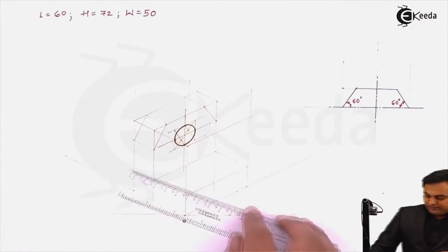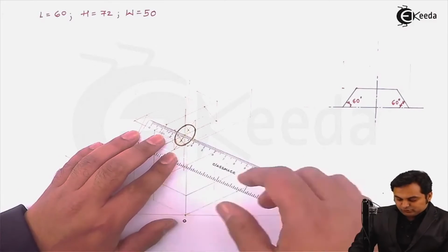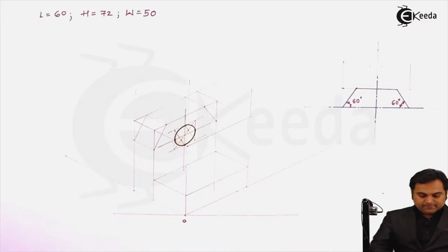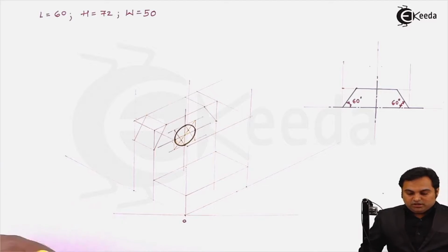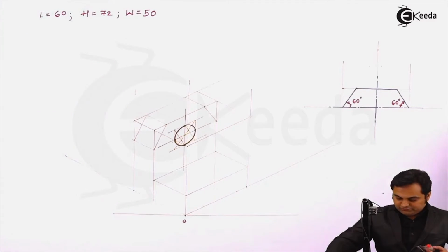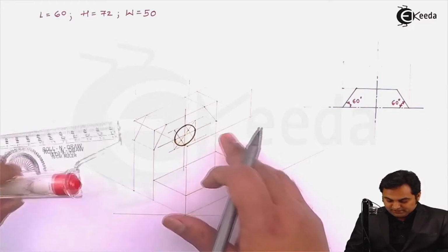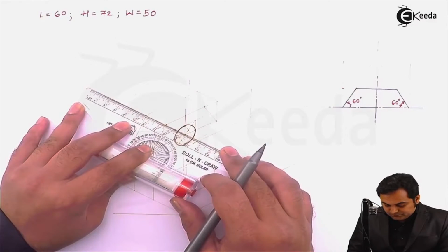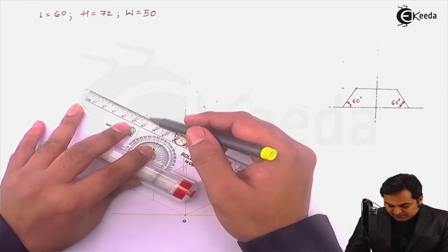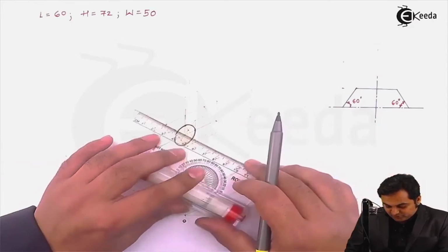And suppose instead of that, if I take the top center ahead and try to draw it, I'll explain how it should be done, because we have to check the depth whether the circle would be seen along the depth or not. For that, instead of taking the bottom center as I've explained, it is crossing the diagram, and here I'm taking this top center with the help of light line behind, measuring 20 mm over it.